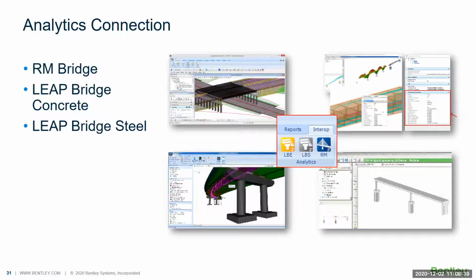And the important thing is after the analysis, if there's any change in the analytical models, we have the loading analysis. If you find that you need to edit it, so you need a higher loading, then you just add it in RM Bridge or LEAP Bridge and feed it back to the model. The model will continue to update. So that's why we have a bridge model which is linked with our RM Bridge Designer as well, from the physical models to the analytical models.